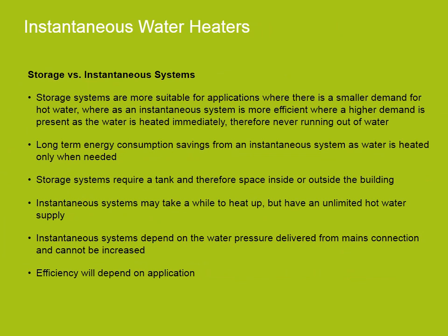When comparing storage systems to instantaneous systems, storage systems are more suitable for applications where there is a smaller demand for hot water, whereas instantaneous systems are more efficient where a higher demand is present, as the water is heated immediately, therefore never running out of water. There is a greater opportunity for long-term energy savings from an instantaneous system because water is heated on demand. Storage systems take up more space as they require a tank to store the water. Even though instantaneous systems have a startup delay, they can provide an unlimited hot water supply.